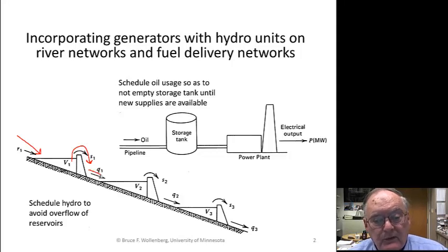Q is the water that comes through the turbines, and there can be multiple hydroturbines. We have not in this particular chapter dealt with the fact that hydroturbines have a unit commitment type problem. And if you do have a hydro unit commitment problem, then oftentimes people go to Lagrange relaxation to solve the hydro problems, because they're doing on and off scheduling. Okay, and these plants here, we represent the output of this. All of the spill and all of the Q goes into the reservoir at a lower level along the river, and then the same thing down here until it gets discharged finally into the lowest level of the river, which eventually will run into the ocean.